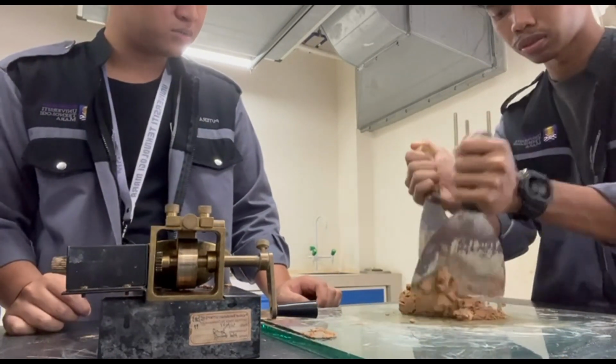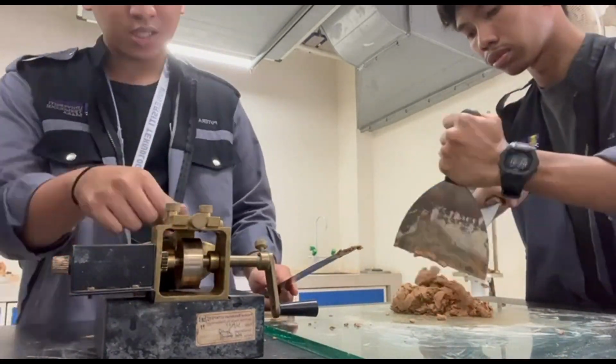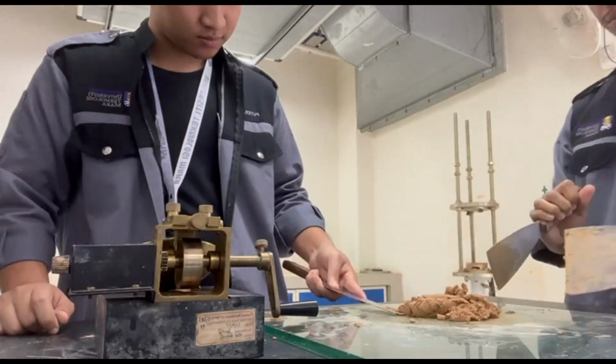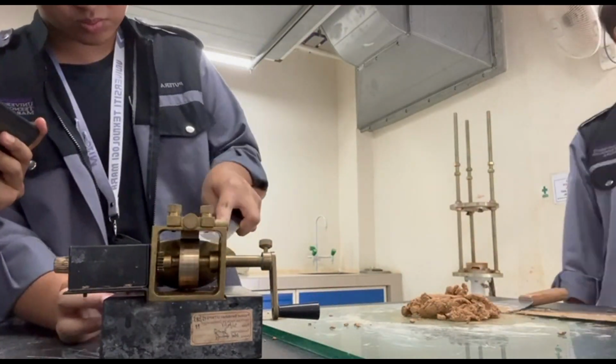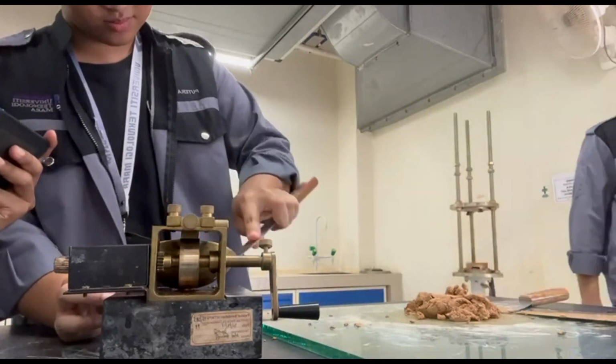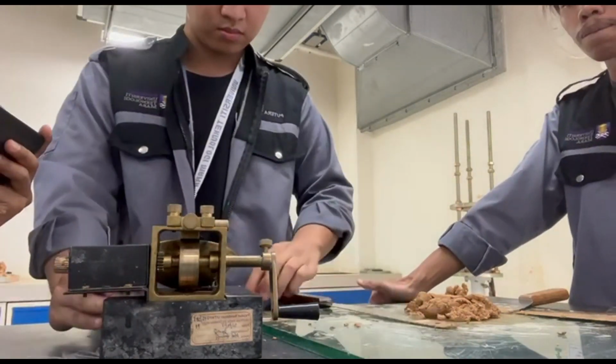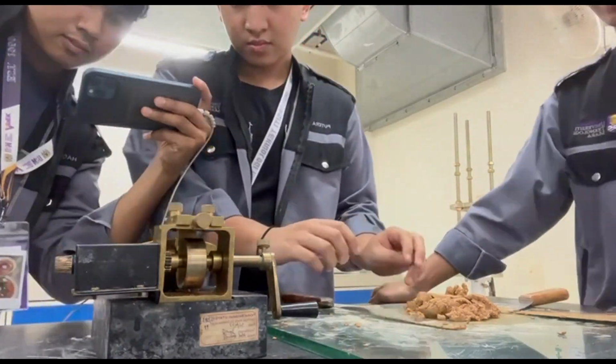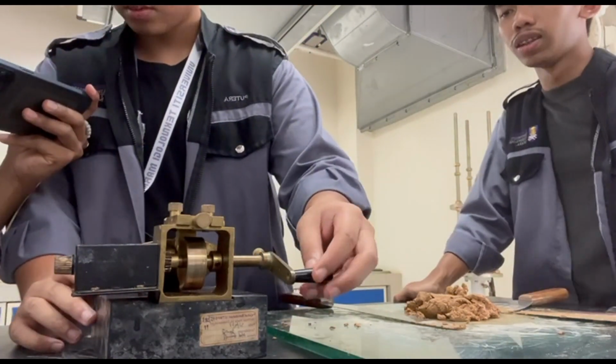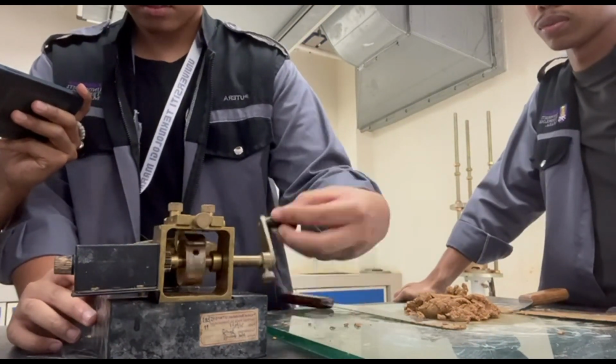The steps were then repeated for 2 additional trials, producing successively lower numbers of drops to close the groove. One of the tests shall be for a closure requiring 30 to 40 drops, one for between 20 to 29 drops, and one for a closure requiring 10 to 19 drops.